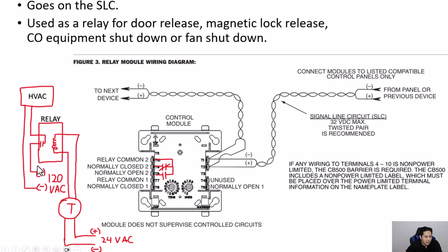So it could be inside a condensing unit or an indoor fan unit, and it would basically just turn on the system. So when the current goes through this coil in the relay, it magnetizes this coil, which will flip this switch to close, basically sending the normal power to the HVAC system. Again, this could be a condensing unit or it could be a fan indoors. So this is generally the way that you control the HVAC system from the low voltage thermostat wiring.